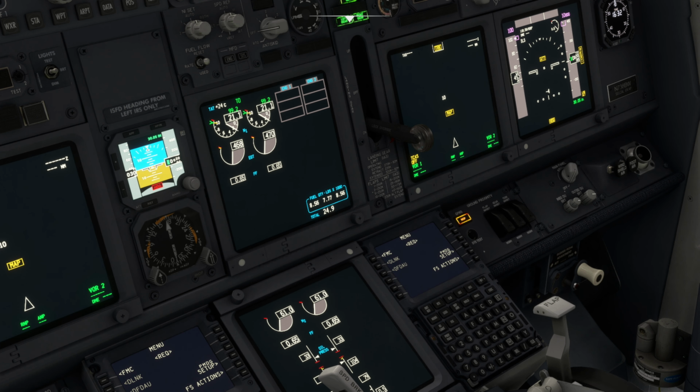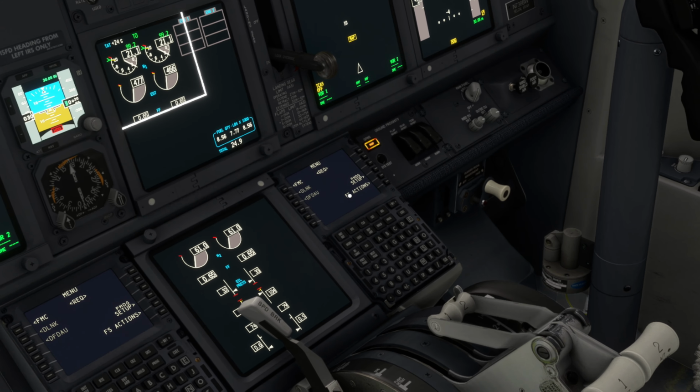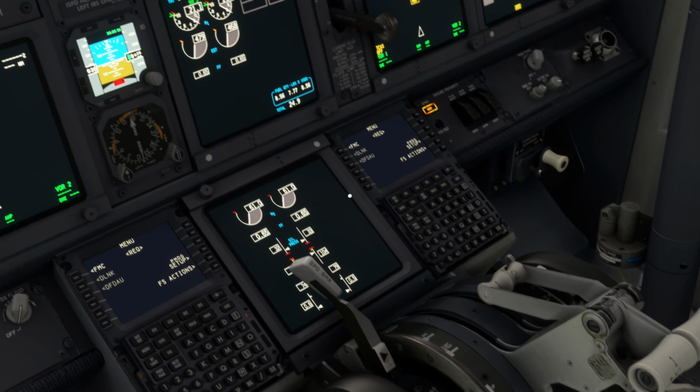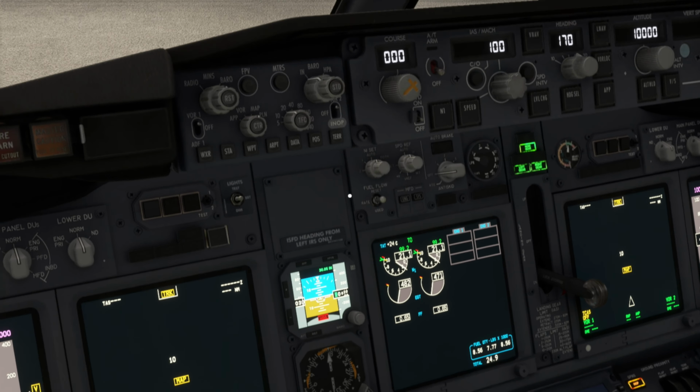So what this tells me is that this airplane had very little, if any, hydraulic pressure available at the time of its attempted belly landing. Obviously, we don't have any landing gear deployment. The landing gear doors are not open.